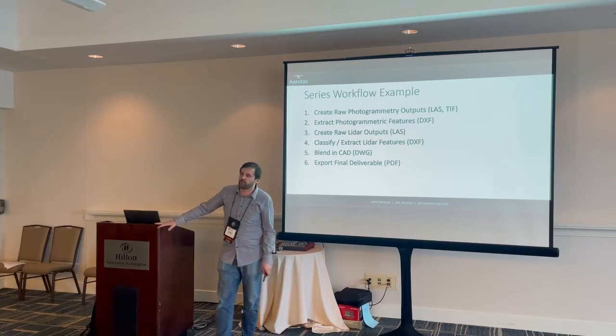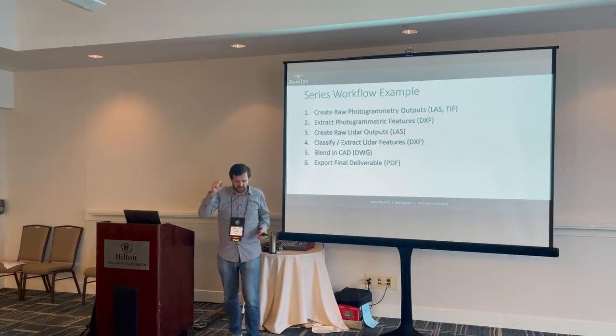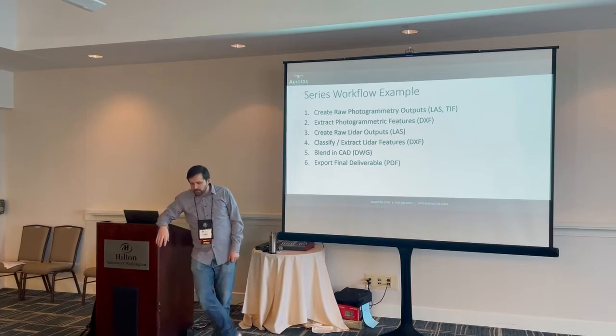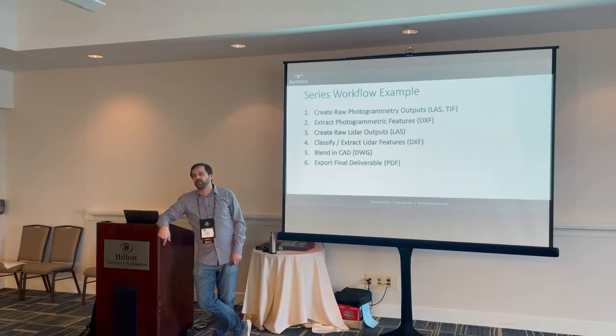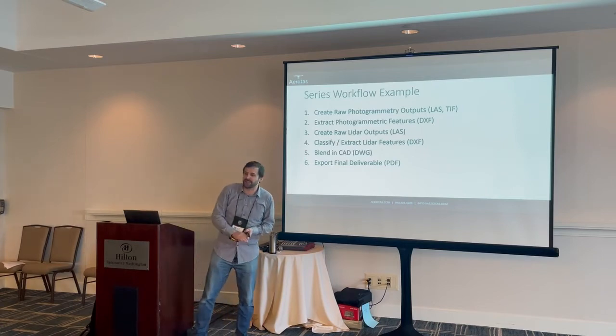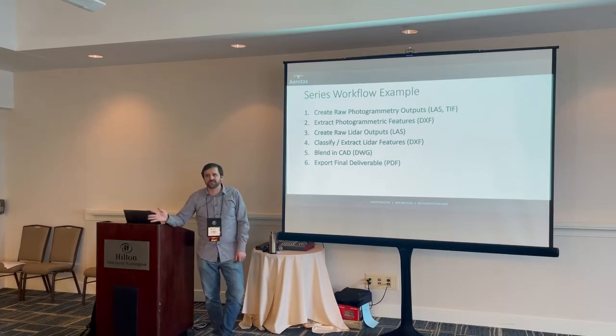So you can use a software like Global Mapper. We like Global Mapper. It's a very compatible format. You can put orthophotos, surface models, TIN surfaces. You can throw basically anything at it and it'll be able to open it up. But switching back and forth regularly between getting it from the orthophoto, getting it from the point cloud, creating grid surface models and elevation models, trying to draw break lines in 3D, it's just time consuming. That's the only reason we don't do it like that regularly, not because you can't, but because it takes more time. So yes, we do often blend the two together.